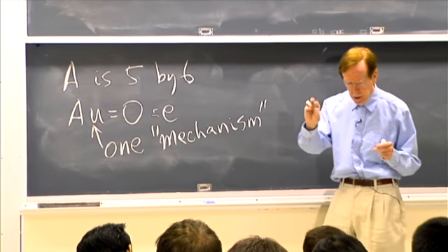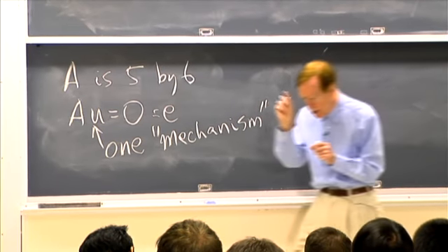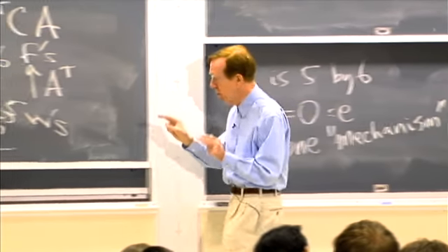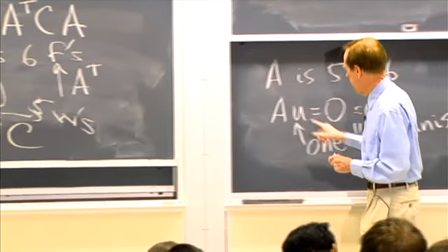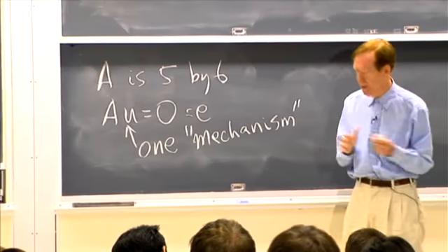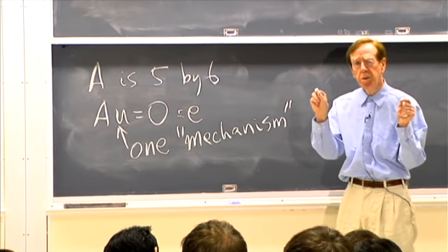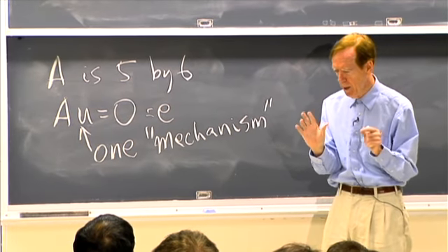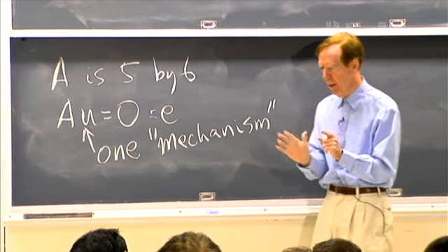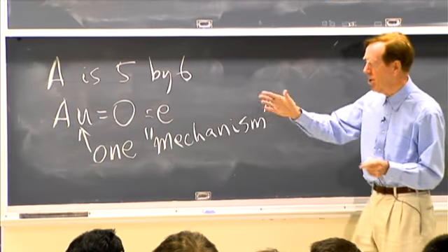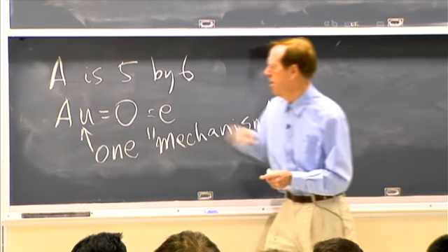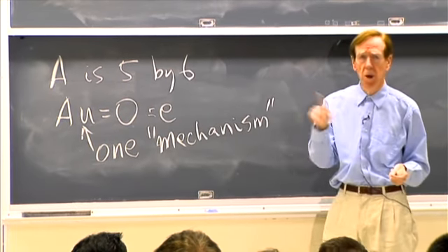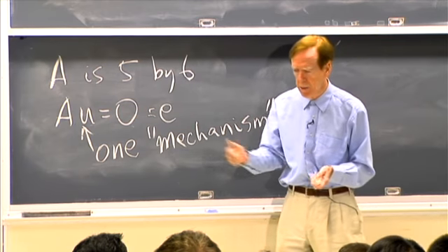The bars are going to move a little. The nodes are going to move a little bit in this U, because it isn't 0. But the bars won't stretch. So that tells us we've got instability here. Of course, if there's a solution to that, that's always telling us that A transpose A is singular.